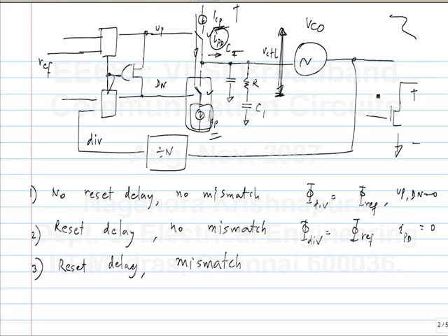So, as you tune the synthesizer or the VCO, the voltage here will change and that will also change the characteristics, but the specification would be that you minimize it to the extent possible. Of course, you can't operate these current sources with zero voltage, so you have to leave some room at the bottom and some room at the top for the current sources.